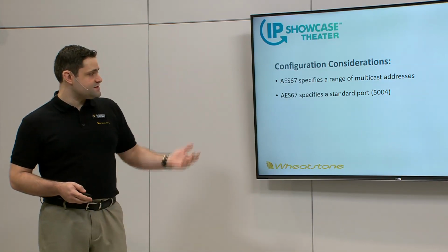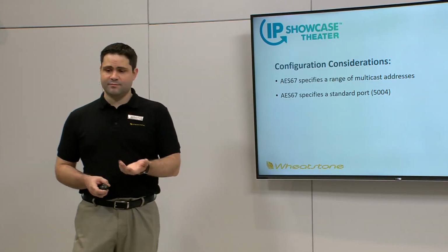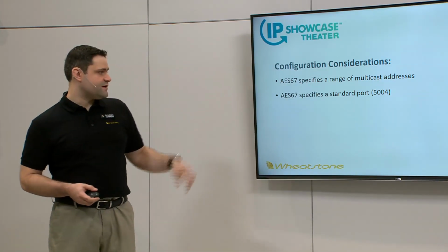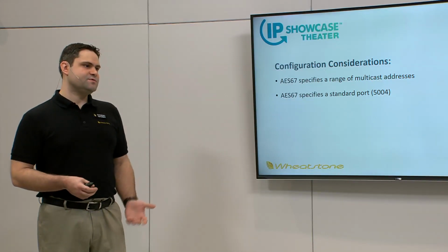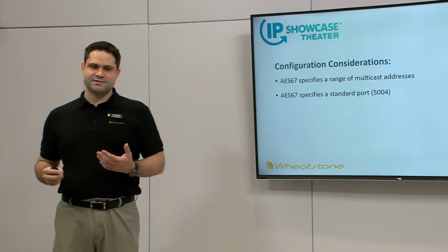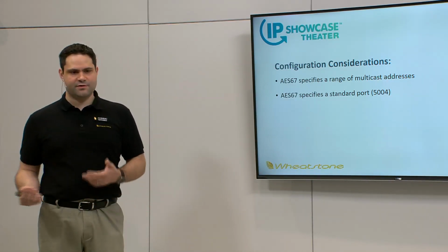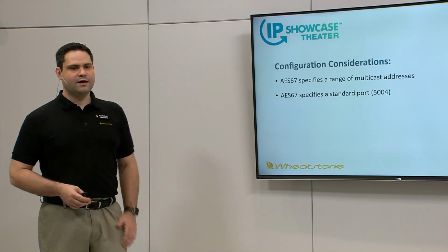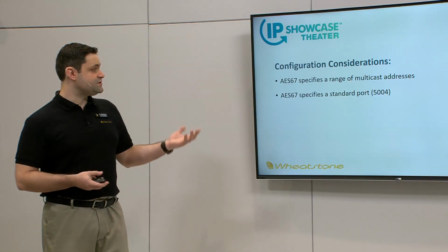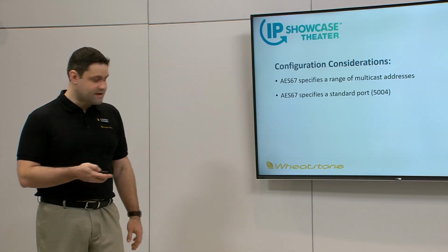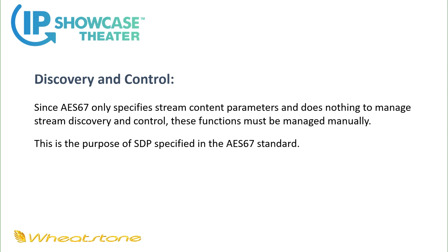And AES67 specifies a standard UDP port, which is 5004. Our system uses 50,100 as its standard, but it can be changed, and we can receive or transmit to any port. So that was a change that was brought about by AES67. Again, discovery and control.